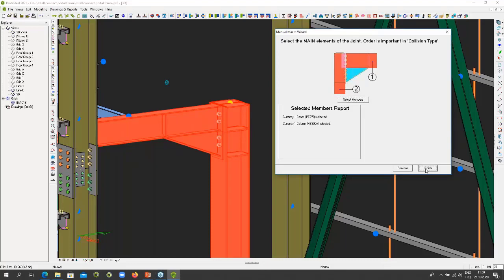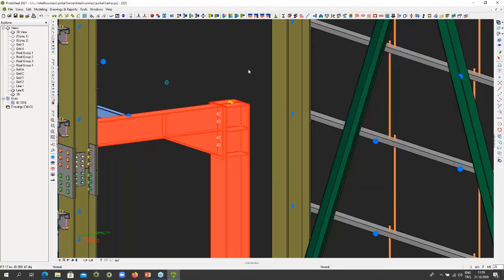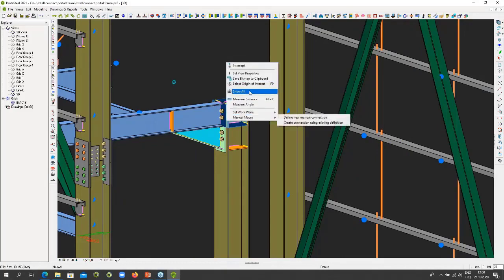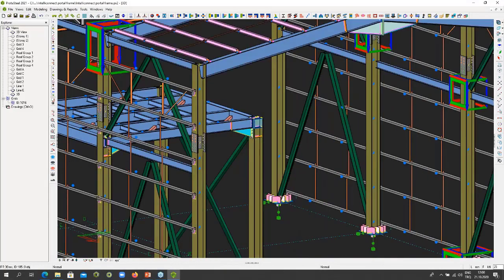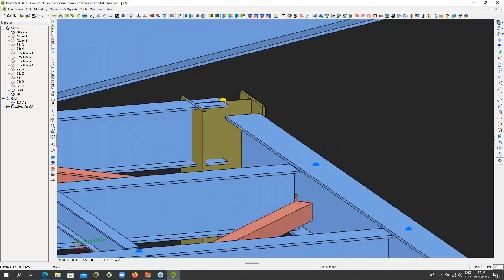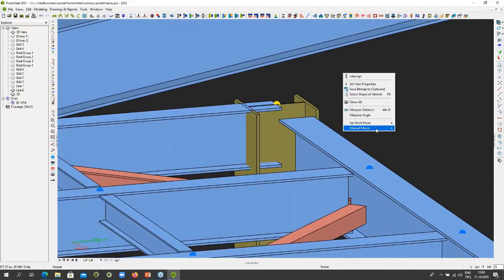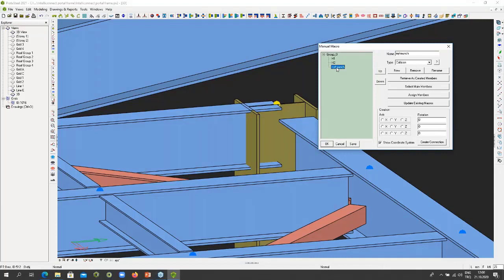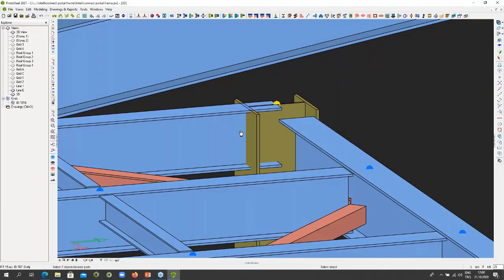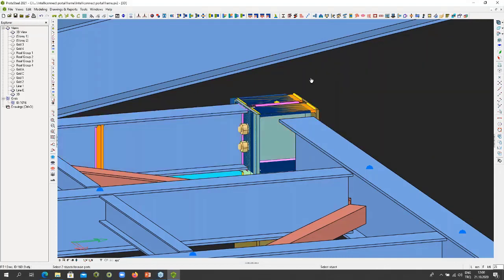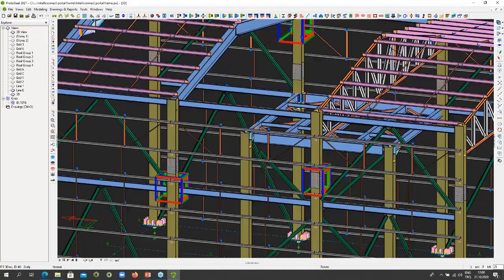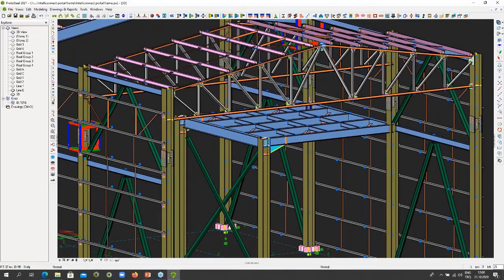So it's turned into a wizard. Previously people were finding it difficult to use, but it's very simple, a simple iterative process. Let me just show all again. Now this connection which I called my haunch, I can just go over here and say create connection using existing definition, and my haunch is there. I can say create the connection, using this beam and this column, and immediately my haunch is created. So it's extremely easy to create your own library of connections.